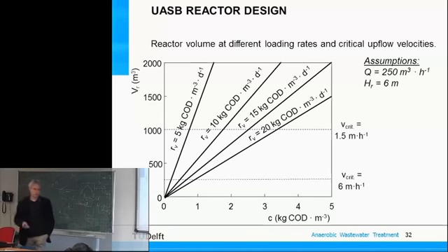And if you recall the lecture of Merle de Kreuk, then she also said, okay, if you have granular sludge, you don't need these big clarifiers anymore. Which is the same in anaerobic reactor technology. If you have granular sludge, you don't need the big reactor volumes in order to retain the sludge, since they settle by itself.